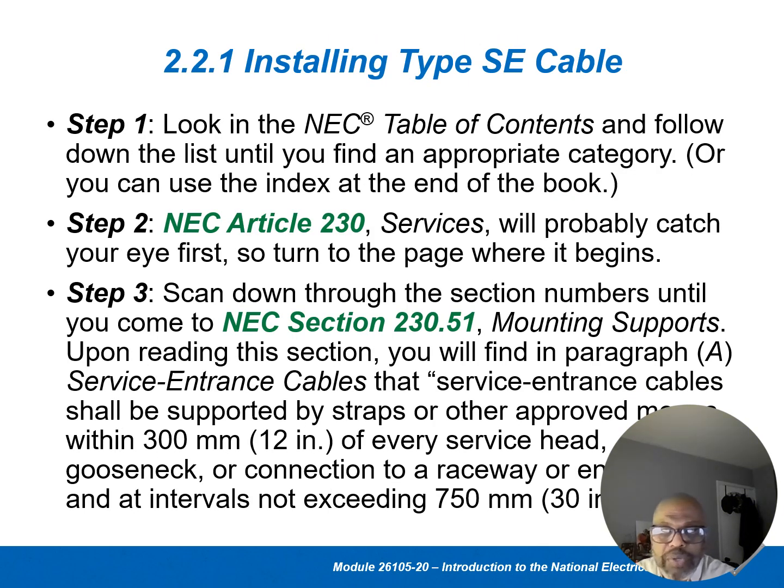So, installing type SE cable. SE cable is a special cable. It's flexible, has a rubber coating on it, and is used with multiple conductors in it. So look at the NEC table of contents and follow down the list until you find an appropriate category, or you can use the index at the end of the book, and that's a lot of times the best way to find something very specific, because the index will tell you exactly what page to find it on. Step 2, the NEC Article 230.